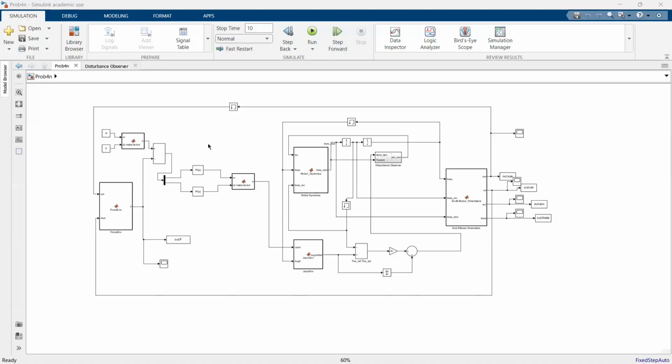Then what happened in the X, the wall: at the collision at 1.5 seconds, the robot hit the wall, causing a massive brief force spike of 37 Newton. The mistake was that the robot was programmed to pull on the wall with negative 6 Newton.